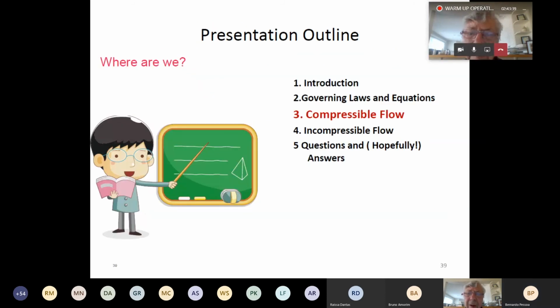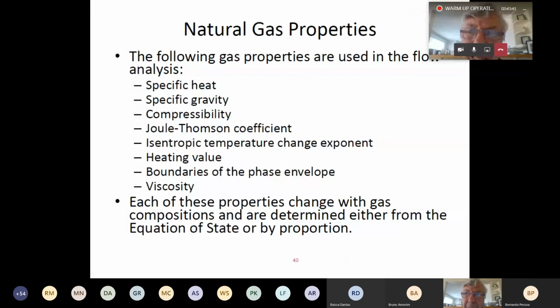And then we'll find there's another phenomenon called the Joule-Thomson effect when we've got throttling of flow, when the pressure drops from high pressure to low pressure, there's an associated cooling that goes on, and that's called Joule-Thomson cooling, and it's very important in gas pipelines. And even more so if you were ever going to be involved in transporting carbon dioxide. A lot of people with climate change are thinking of sequestering carbon dioxide and pushing it underground.